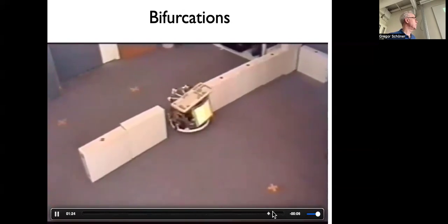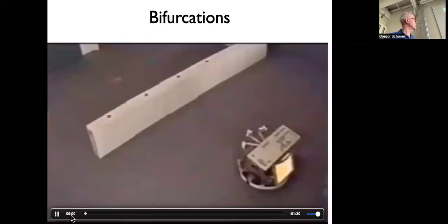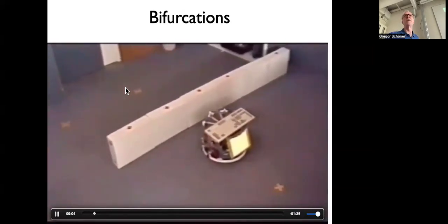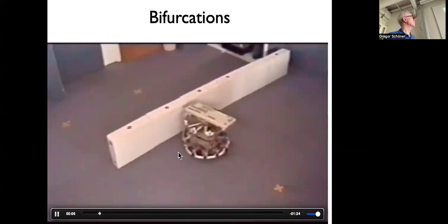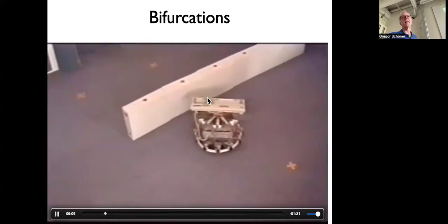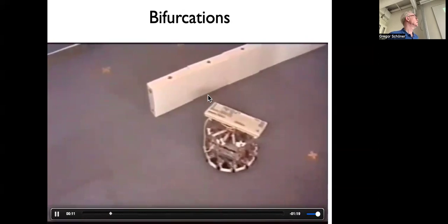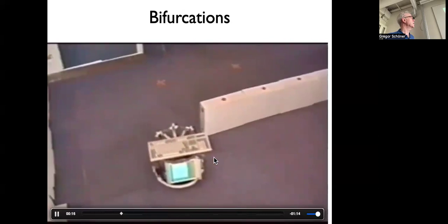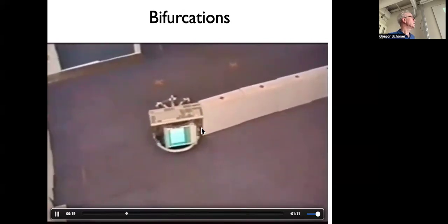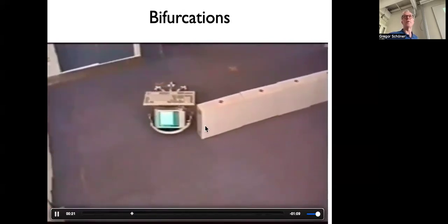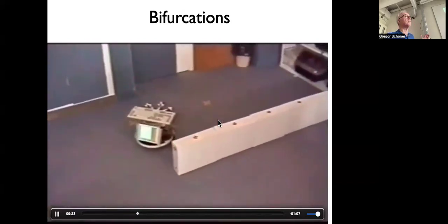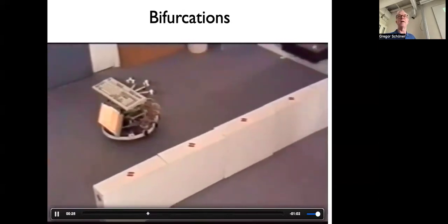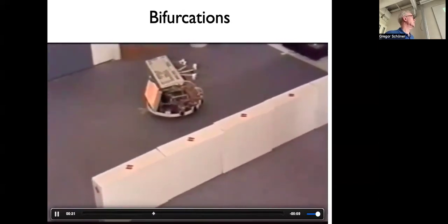So now let's actually really look at the content. So far, I only talked about what the vehicle is like. So here, the target is this cross. This is by dead reckoning. We find that in the robot computer. See, it turns around only as it gets close, because that's when the sensors start sensing. And then it ultimately starts turning back to the target. And see, it almost cuts into the object. Only when it gets close does it get repelled again. It's not a global plan. It doesn't know there's an opening. Just by chance it turns that way and finds the target.